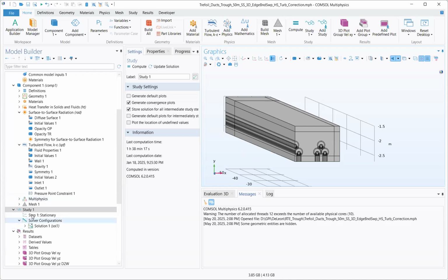And in the case of time dependent simulation of cables in air, where there's a fast transient, the relative tolerance that you set determines the time step, right? So the lower the relative tolerance, the better the solver will automatically adjust the time step to capture those initial fast transients. So you don't need to manually try to force the time step.